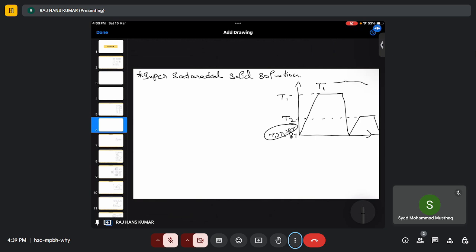Now this whole process is called precipitation hardening, or people even call it age hardening, which is a little bit different. So let's call it the precipitation hardening process, where we quench it and then heat it again to form precipitates. While heating, we can control the shape of the precipitates being formed. Again, how? I will explain in a few minutes. So this is our whole process for why we do precipitation. We can control the size of the precipitates while doing this type of process.